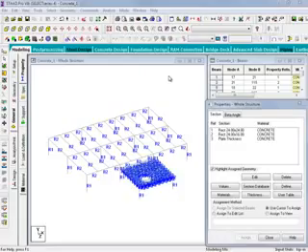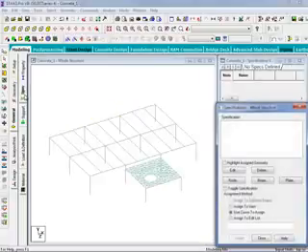To assign specifications to your model, we're going to go over to our page control area, select the General tab, followed by the Specifications sub-tab. Over in the Specifications dialog, we see that we have three buttons available to apply nodal, beam, and plate specifications. First, we're going to apply our nodal master-slave specification.